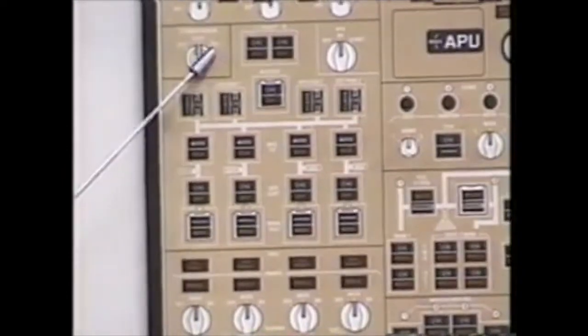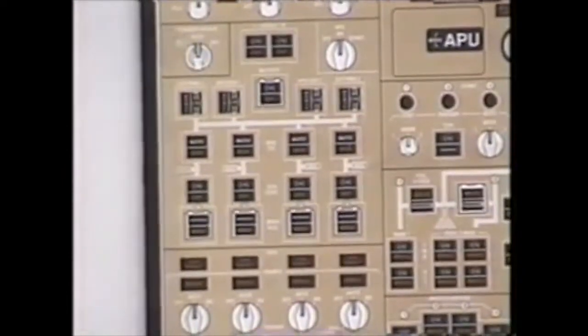It will then position the switch back to automatic, again making sure that the captain's PFD, ND, primary ICAS, and left CDU remain powered, and most importantly that your 2 battery discharge messages go away on the primary ICAS.